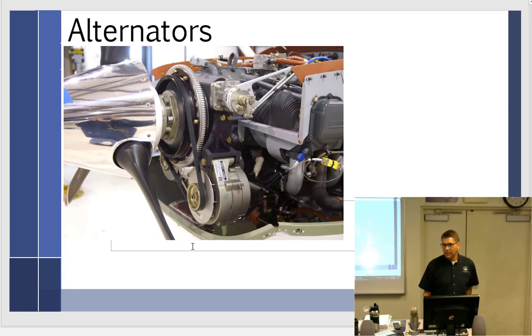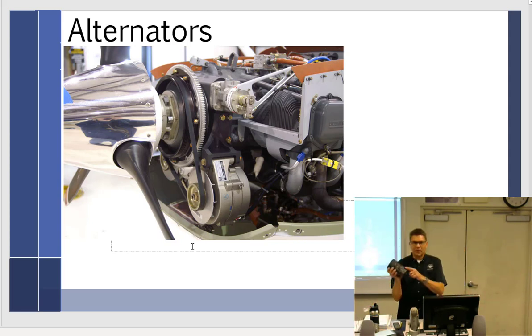But if it's gear driven, like a lot of Continentals, they're gear driven on the other side, right where the cylinder is. It looks like 6 cylinders and a 7th. That's for the alternator drive. And so they're driven inside. So yes, then you have to worry about the seals and make sure that's not leaking. So no oil leaks. Don't forget to take off the inspection band in the back and take a look at it.